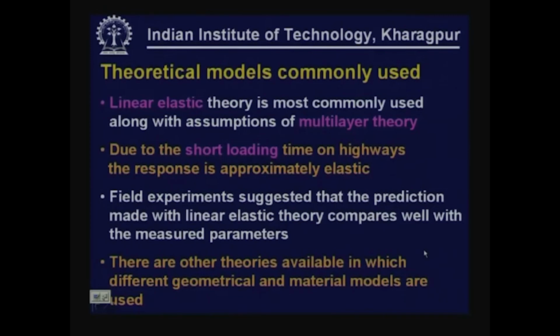The commonly used theoretical models for analysis of flexible pavements are: linear elastic theory is the most commonly used theory, and the geometric model that is used is layered theory. So, linear elastic layered theory is the most commonly used model for analysis of flexible pavements. The layered assumption we understand, because a pavement is a layered system, but we have to justify the assumption of linear behavior of pavements.